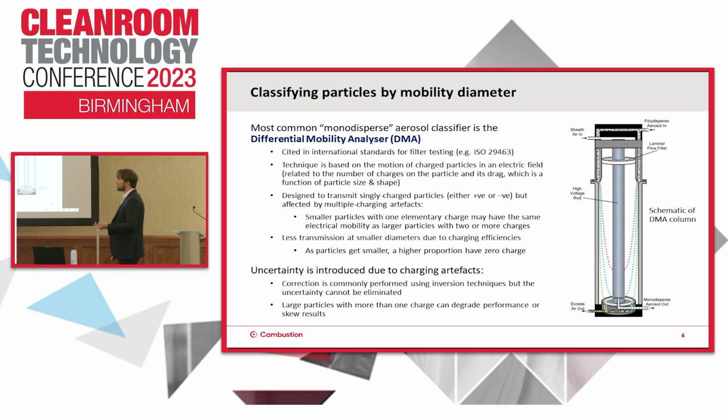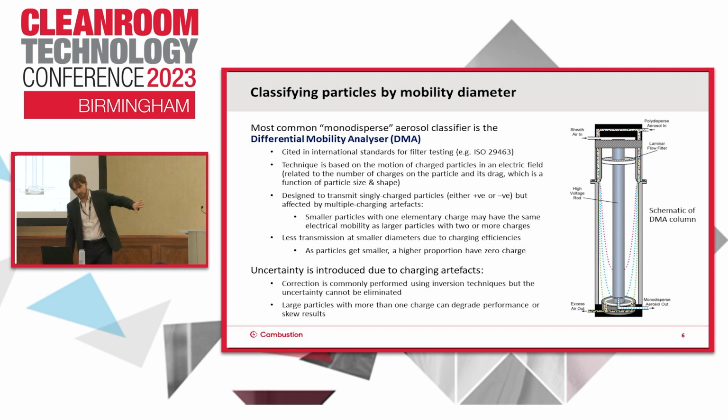Now, the drawback of this technique is, A, you're having to charge condition your aerosol, and you're only looking to pass singly charged particles, so you're having to reject all the particles that are not in that charged state. And secondly, as well as the singly charged particles of the size that you want for your testing, it will also pass larger, multiply charged particles that will have the same mobility. So there you have charging artifacts, multiple charging artifacts that would need to be corrected for.